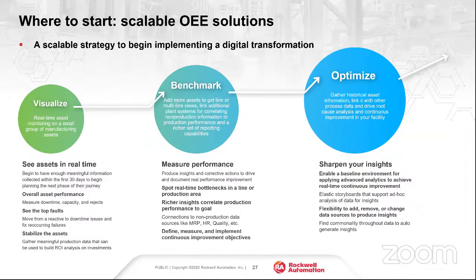Right? So you have a line of 4 machines. Now, machine number 1 is showing that it is at 85% OEE, but machine number 2 is showing that it's at 50% OEE, and machine number 3 shows 50%. But now, do you know which machine actually is the cause? So you can identify that just by looking at the data. So the first step is to visualize that.